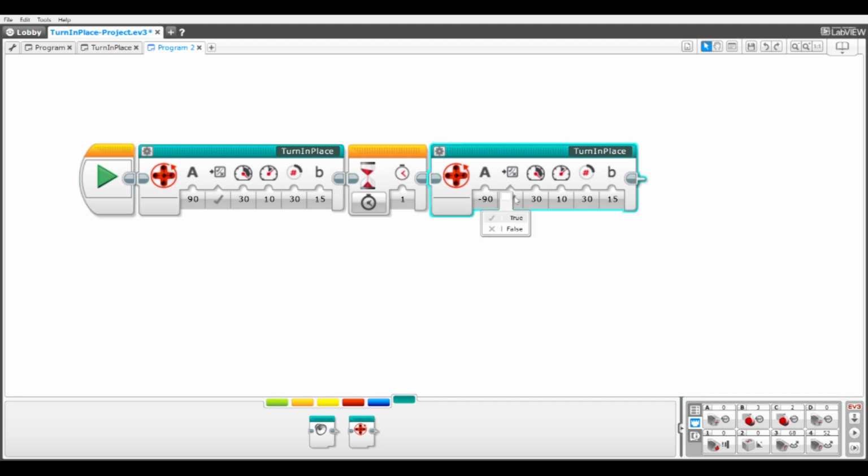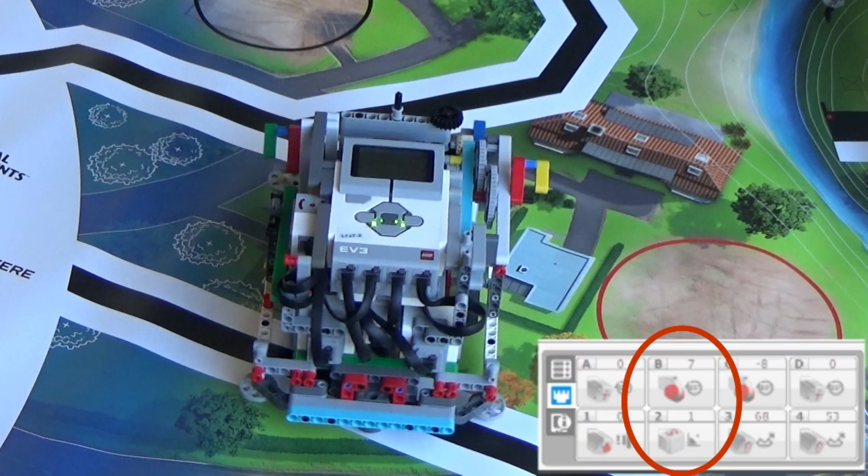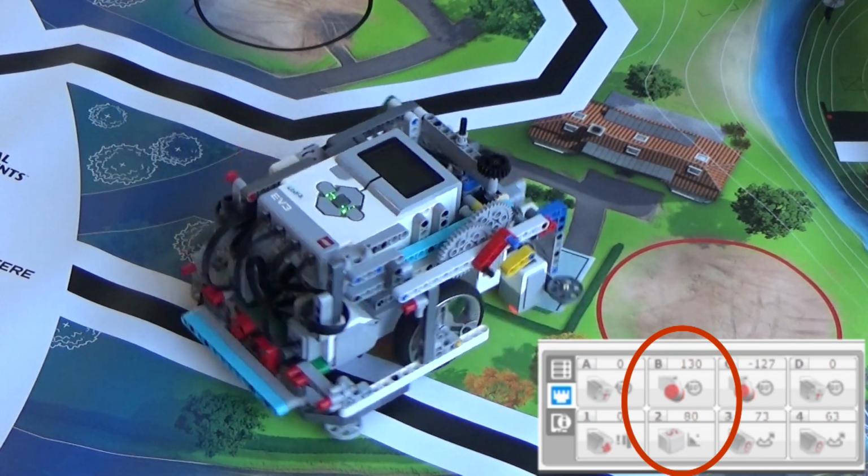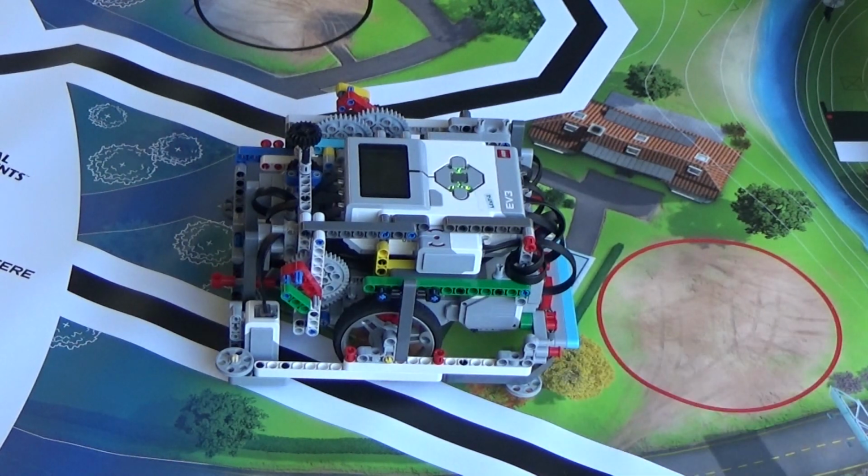When I change the second Turn-In-Place MyBlock move relative parameter to false and run it again, the robot turns 90 degrees, waits, and then turns negative 180 degrees to negative 90 degrees since we told it to move to absolute angle negative 90 degrees. That's our Turn-In-Place MyBlock.